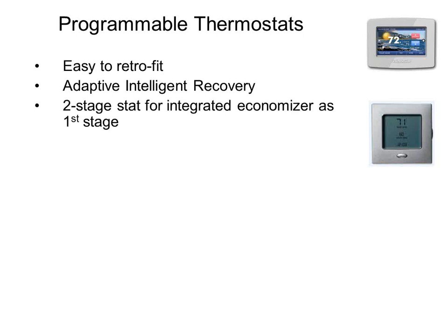You always want to get a 2-stage thermostat in a commercial environment. I realize people do make 1-stage stats. Those are typically residential stats, which, by the way, don't put residential stats in a commercial building. There's numerous reasons for that, and this is just one of them. I need to have a 2-stage stat, even if it's only 1-stage cooling equipment.